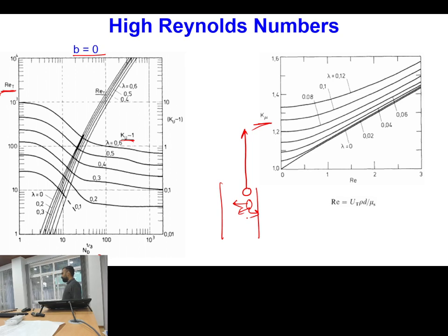But later on, if we consider some particle with fluid inertia present in the system, then we have to also talk about particle migration. You can simply remember, if inertia is not present in the system, then there will not be particle migration. If the particle is located at a certain distance from the wall, it will just follow a straight path at that particular location. But when the inertia of the particle comes into the picture, it will not remain at a fixed distance from the wall, but can migrate either to the center or go to the outer side. What happens with the presence of inertia, we will see in the subsequent discussion.